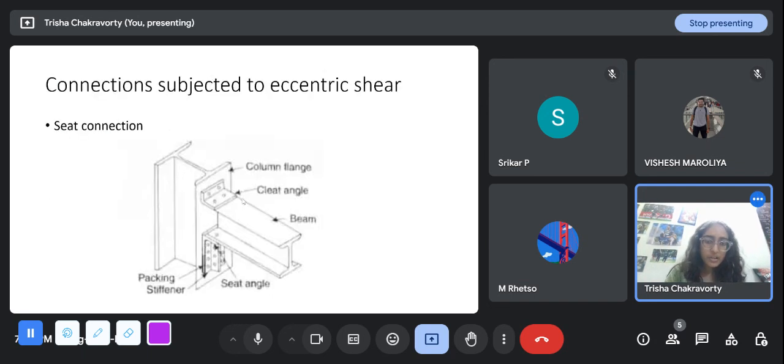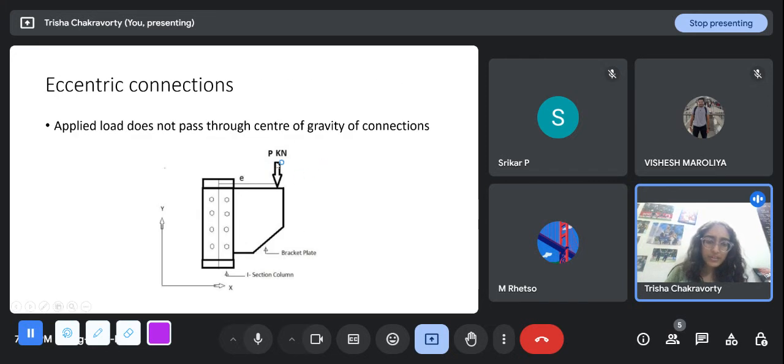This is important. Torsion comes, we know that torsion is this kind of rotating force. So when you apply the load here, if you had applied the load along this line, then the only force that we have to see is the tension and compression along this line that we have done previously, when we were designing bolts or welds. We took the tension or compression along the plate itself.